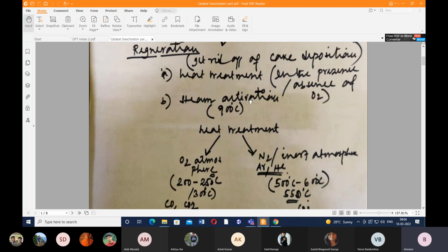So we are conducting a gas phase reaction in the presence of a porous catalyst. Let's assume the reaction is A giving B. First of all, the reactant gas will diffuse from the bulk phase to the external surface of the catalyst. The next step would be diffusion from the external surface of the catalyst to the pore mouth.